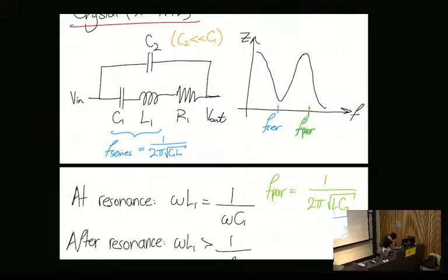From here to here, we are capacitive. Then from this region to this region, we are inductive. And then again, because that capacitor is a very small number, it's effectively going to look like a short at high frequencies, and so it's going to dominate. All the current is just going to want to go through that capacitor there. Sorry, no.